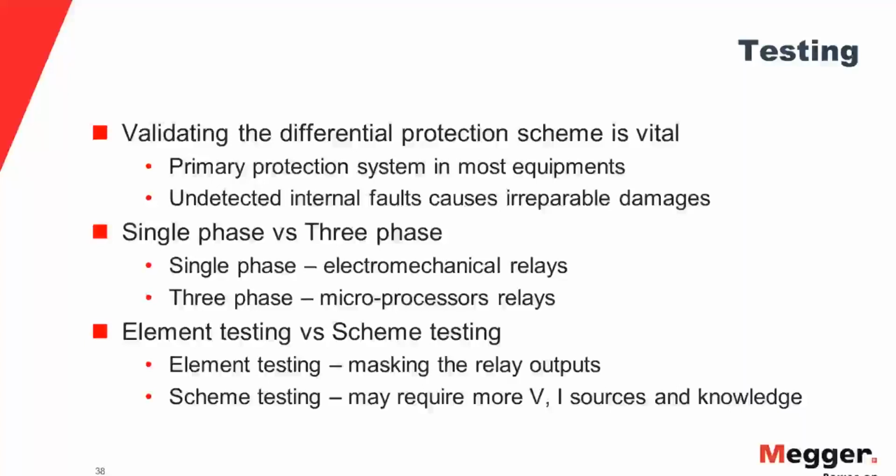Now there are two schools of thought on that. Do I test single phase or do I test three phase at the same time? Typically, when you're dealing with electromechanical relays, you test one phase at a time. So it might be a single phase test that you perform, because a phase will have a certain either Westinghouse or ABB Westinghouse or GE relay in the system. So you have single phase covering for one, either A, B, or C phase.